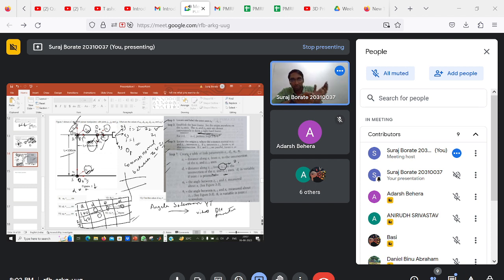If z1 is inside, x1 has to be rotated by 90 degrees to reach x2. About the z axis, with the right hand rule, x1 has to rotate by 90 degrees. So this is plus 90, and because it is a joint, it will be 90 plus theta.